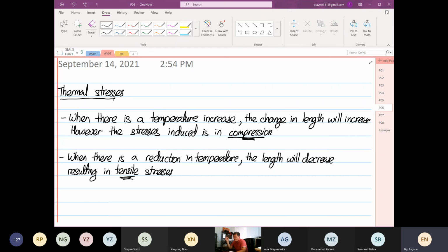That's why if you look at in Canada, we have those overhanging cables where we carry our electricity. And I still remember in the year 2013 or 2014, you have heavy snow and rain and freezing rain again, and then all this effect, and then the temperature dropped to -20, and then our cables break, because of twofold: the load of the ice and also the temperature went down very low.